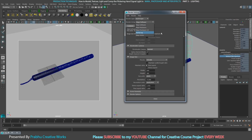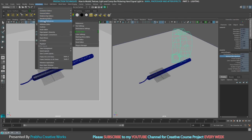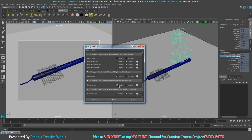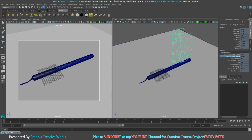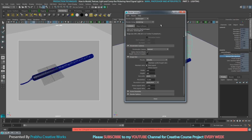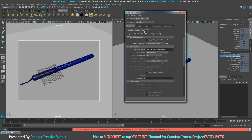Sometimes it will not appear here, so that means you want to enable it in the plugin manager. Go to window, settings preference, and choose plugin manager. Here you want to enable Maya to MR. Check these two options and close. That means when we go to render settings, it will be available here. Choose this one. Once you close and reopen, it will update.